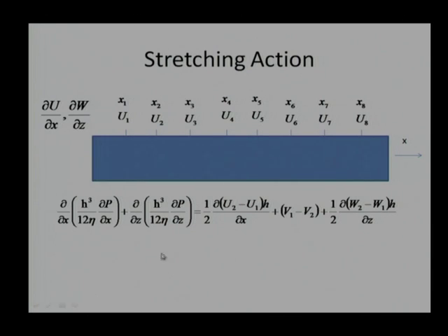If I want to represent it in the Reynolds equation, which was explained in the previous slide, we can write this term and partly differentiate it. First, differentiation of h with respect to x, and then in the second case differentiation of velocity with respect to x.